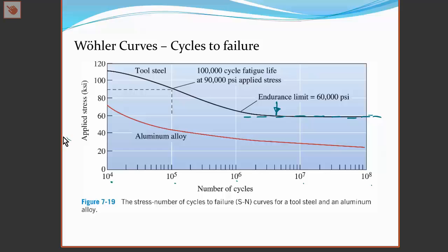And this has importance for aircraft, for instance. If you think of the vibrations that the skin of the aircraft, the wings and the structure of the aircraft is susceptible to, and also what happens to the fuselage every time it is pressurized and depressurized. So the life of aircraft is actually not measured in hours, but measured in terms of the number of pressurization, depressurization cycles. Because the failure mode of the material, of the aluminum material that is used, or is still widely used for aircraft skins, is aluminum, or an aluminum alloy.